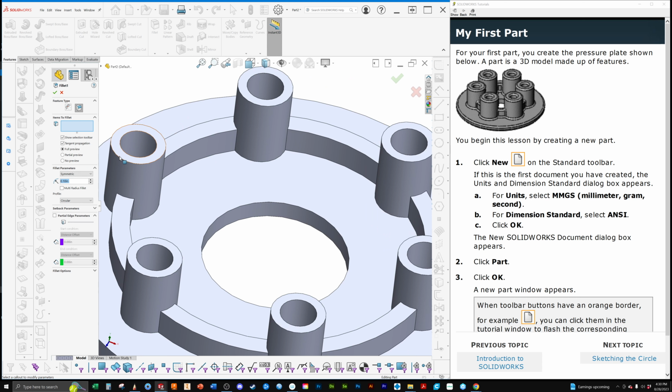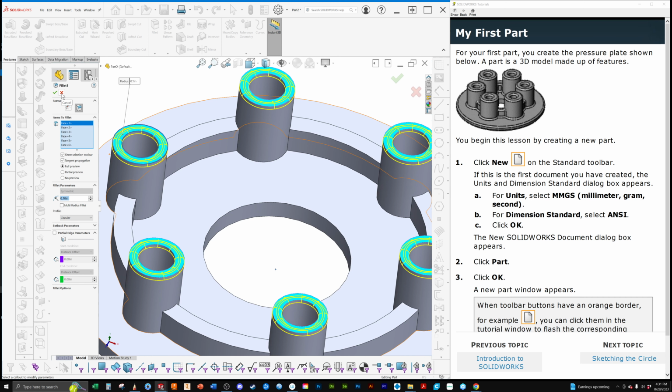The problem with doing that is, if you look at your model and you come back and say, well, I really want that inside edge to be sharp, now you don't have a choice, because one face controls it all. So as you're looking at things and trying to figure out where things should be, you want to break it out. What areas are you going to want to apply radiuses to where you might want a different size? Or, hey, I want this to be nice and round here, so you don't want just one radius on everything.